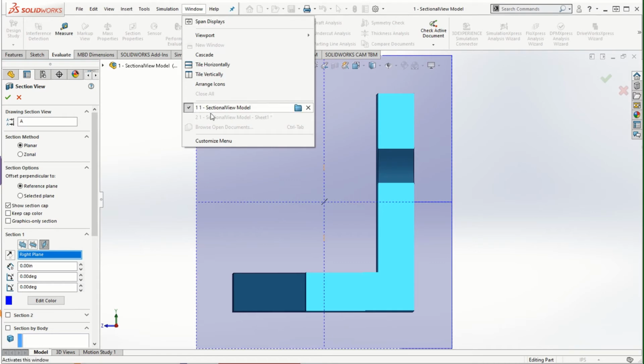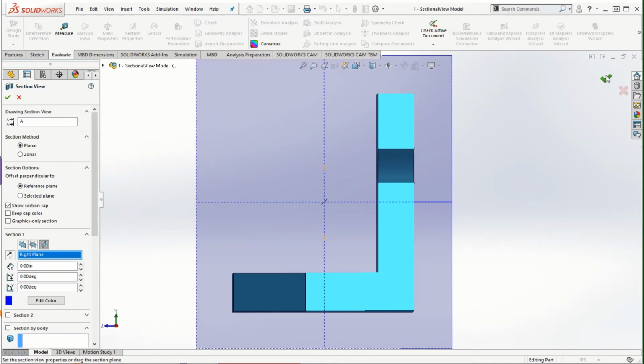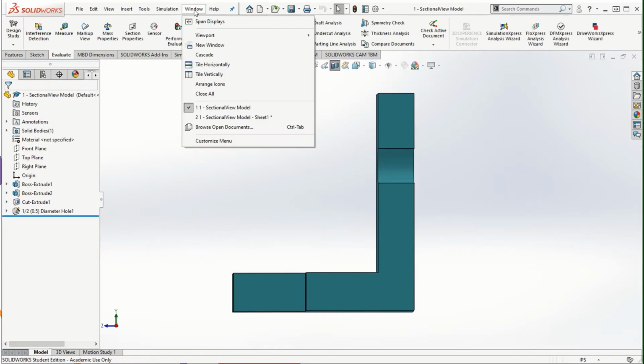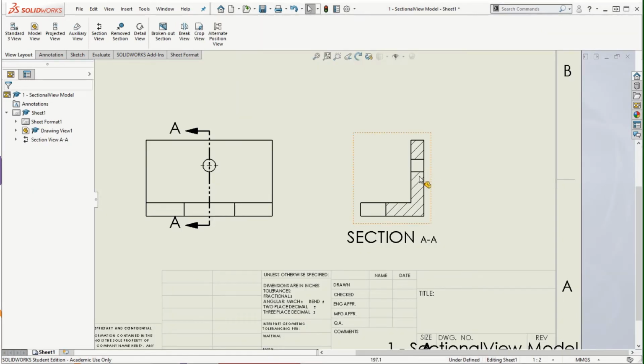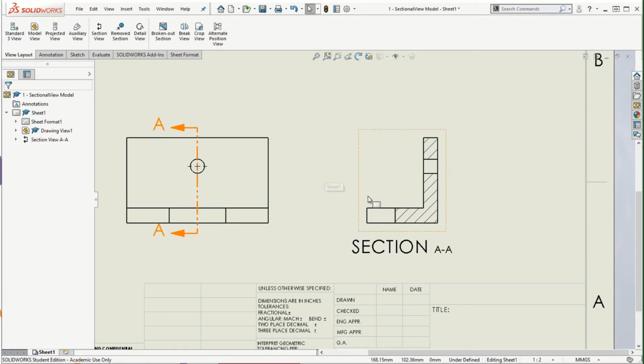If I go back to the drawing view, that is where we can confirm the sectional view. Sometimes it's easier to show the sectional views rather than the normal right view or any other projected view because of several hidden lines in the geometry that make it difficult to visualize the dimensions accurately.